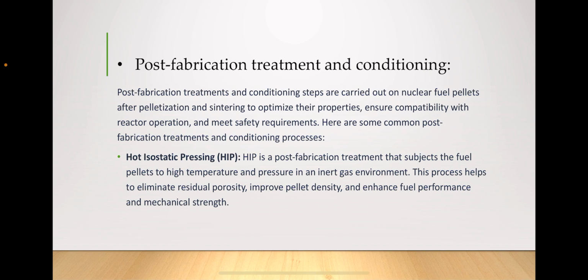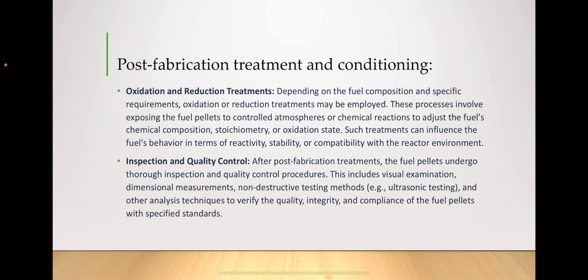Hot isostatic pressing. Hot isostatic pressing is a post fabrication treatment that subjects the fuel pellets to high temperature and pressure in an inert gas environment. This process helps to eliminate residual porosity, improve pellet density, and enhance fuel performance and mechanical strength.